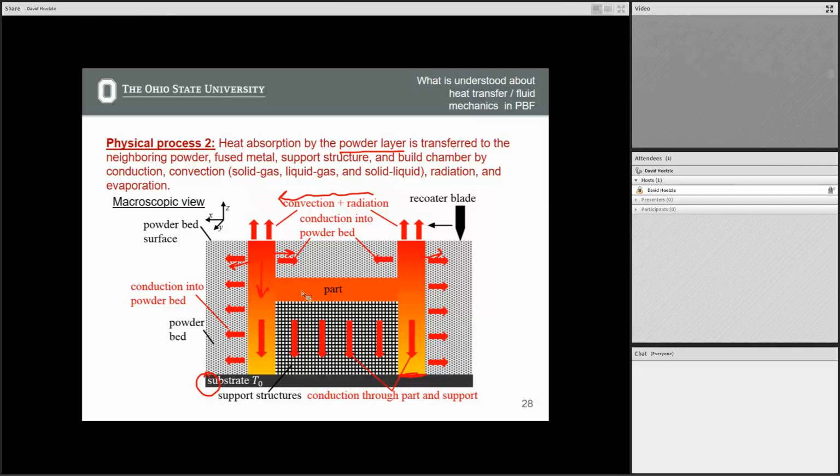So, like I said, if we have overhangs, like say anything less than 35, 45 degrees, that causes a big problem. So, of course, anything less than that, we're going to have support underneath it to allow the heat to dissipate from that region effectively.